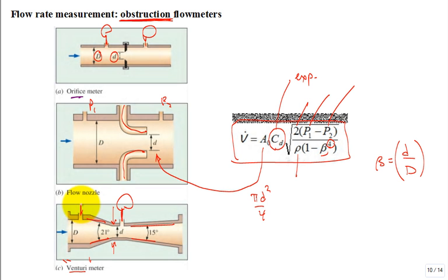The pressure in the throat is lower in a Venturi. But then there is going to be some pressure drop in the Venturi. You're going to try and measure it because you're going to slow down the opening up. Maybe it's a 15% opening on the Venturi flow meter so that you avoid separation.